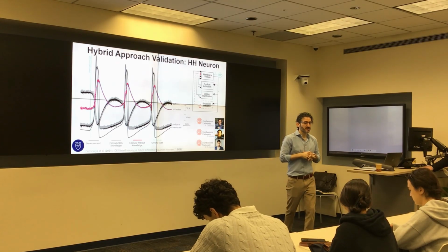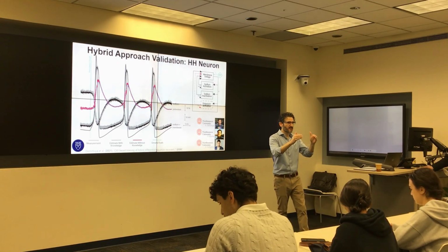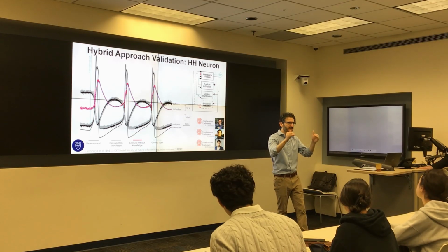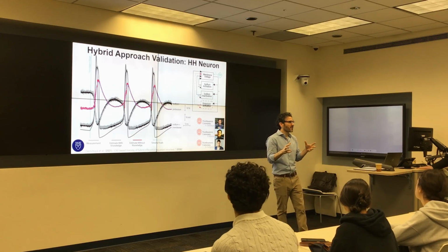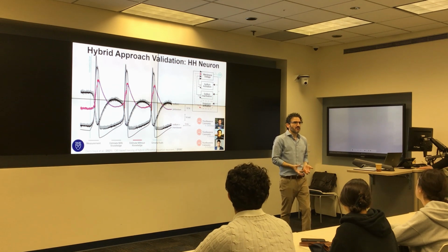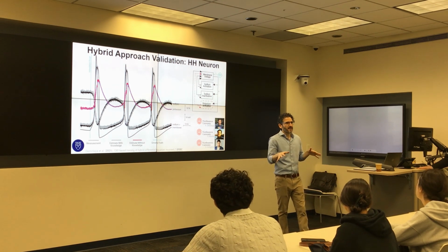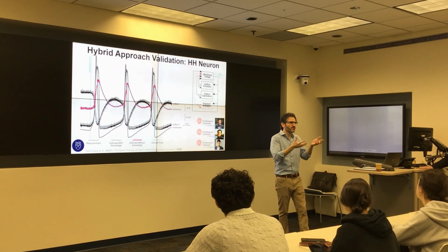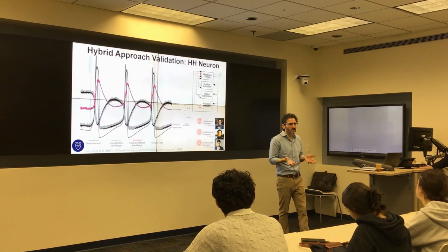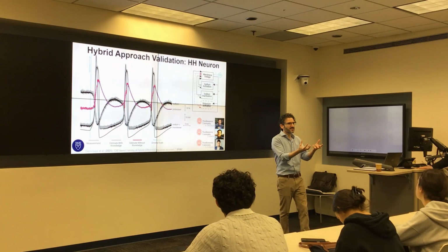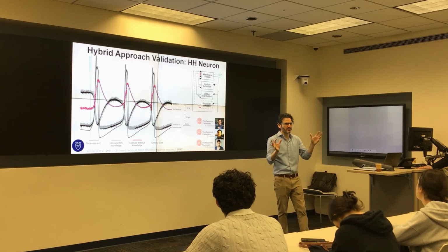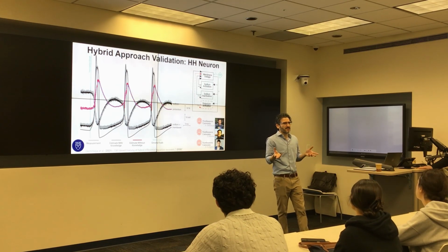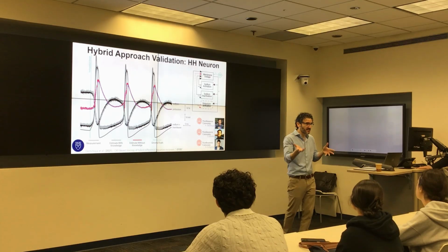The second one is about the Kalman filter innovation. If you remember back to your statistics class, when you fit a line or a model to your data, what you're hoping for is that the mistakes you make look like a bell curve. That says that you can't do any better or worse, all that's left over is noise. If the errors that you make have a lot of structure in them, that's a sign that you could do better with your model, you could fit that structure.